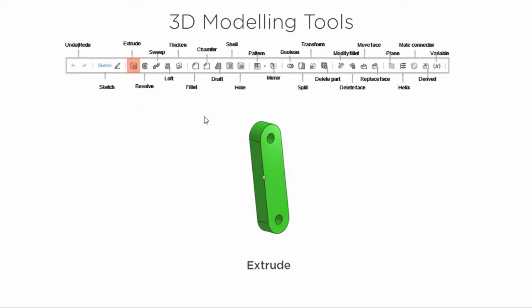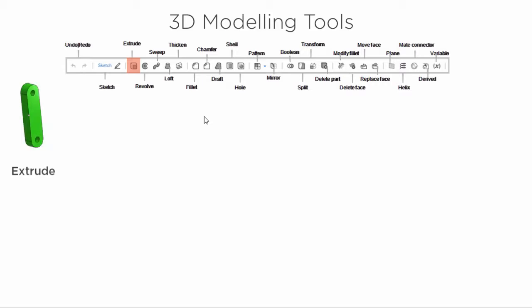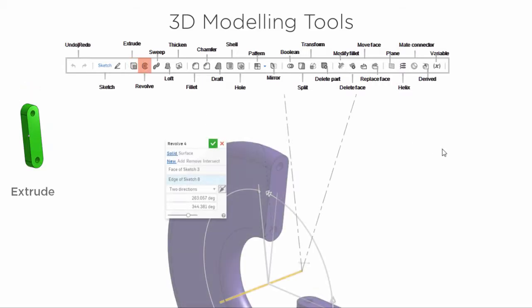Next, let's use the revolve tool to revolve your sketch around various axes. You'll have the same 3 choices, but now need to select the revolve axis. In the drop-down, you select what kind of revolve to apply. Often you will use full, which is 360 degrees, but in our example we'll use a 2-direction revolve, allowing you to provide 2 degree values to specify the opening.